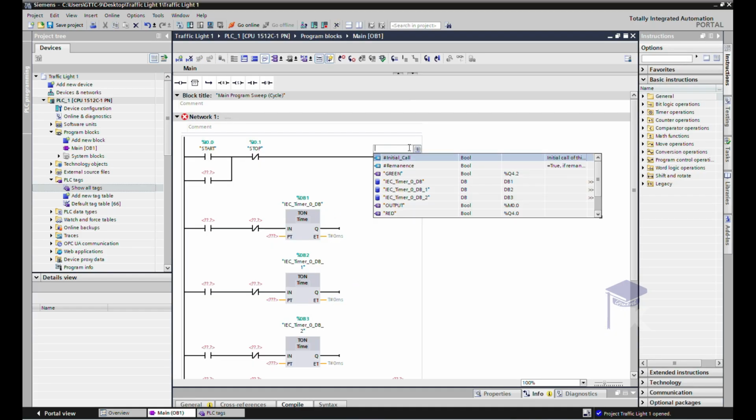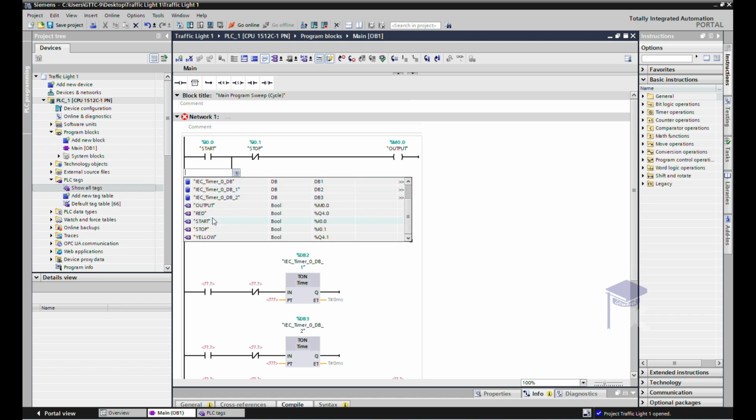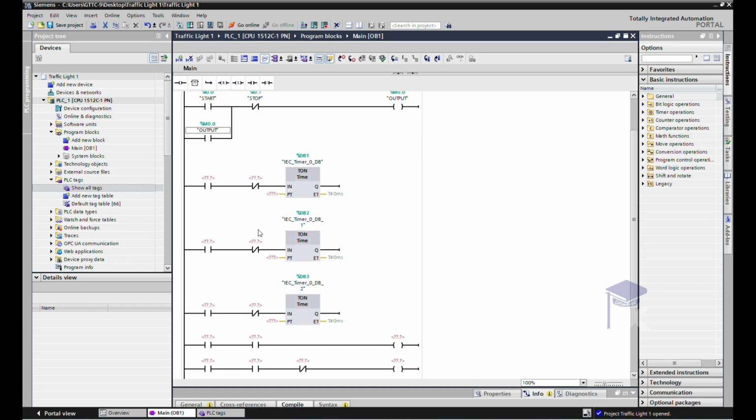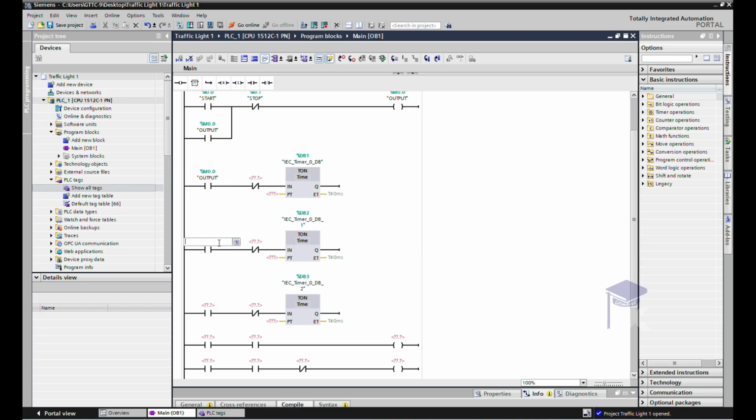So let's go to the ladder logic program. Then click here on this option and search the output, that is your memory address. So my output is this. I will click here. Now I have connected in this latch form. So this same output will come at the downside. You have to give the same address, follow the same steps, and it's done. For all these programs, all ladder logic, we will be using a common memory address and common connection as an output. So assign it to all.